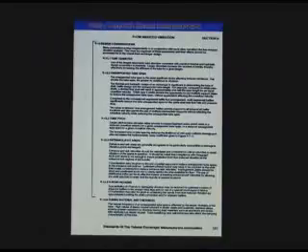So Q equals mCp delta T has to balance between shell side and tube side streams, and on your overall heat transfer coefficient or heat transfer equation. So all three Q values have to balance. That's a good question. I probably should have added that in there as a supplemental energy balance.